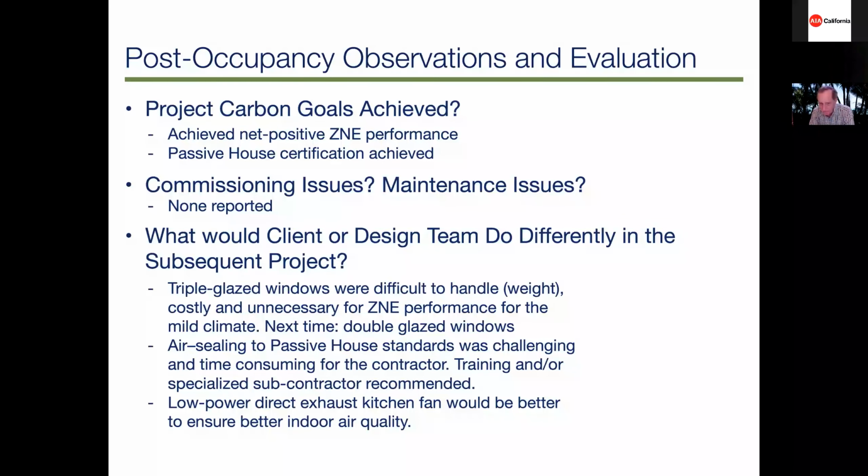They very often and very regularly have a subcontractor who specializes in air tightness come in and give a talk about it. And you can find out who they are and get them to advise you if you're going for a very tight house. And they can also provide the training for your contractor. So on one job, you get the benefit of learning what to do, and also the contractor gets a bit.